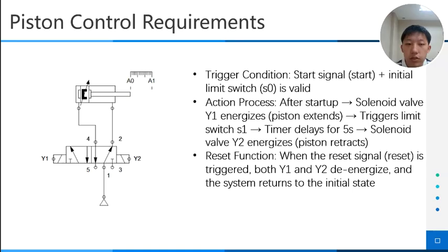Third, the reset function. When the reset signal is triggered, both Y1 and Y2 are de-energized. The whole system returns to the initial state directly, and the piston stops all actions.